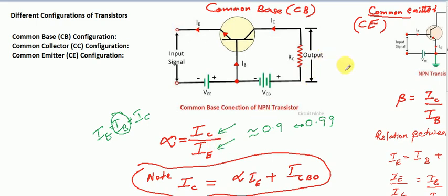As a note, in the collector region, other than the current reaching from emitter to collector, there is another current also, produced due to the reverse bias, because we know that the output circuit is reverse biased. In reverse bias there will be a small current, as we already learned in the case of diodes, due to minority carriers.